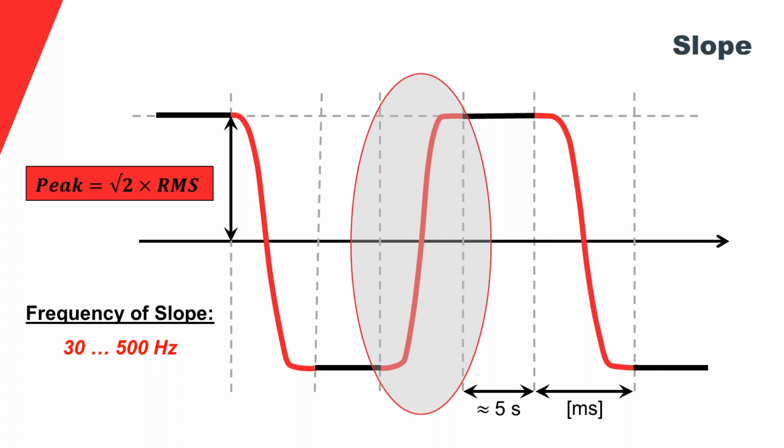And let me just make one thing clear, also calling back to the other webinar. When you do a VLF withstand test, both waveforms, 0.1 Hertz sinusoidal and 0.1 Hertz cosine rectangular, are equivalent and getting equivalent results if you apply the IEC testing conditions, which means everything is scaled in RMS values, which means that the peak of the sinusoidal is 41% higher than the cosine rectangular, because then the RMS value is the same.